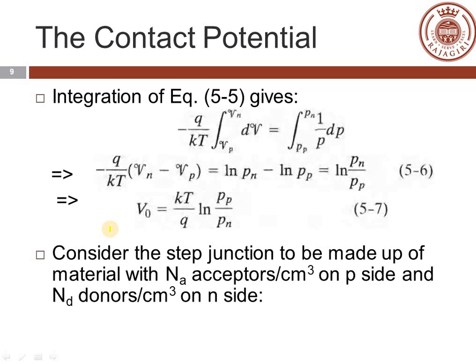Then we can write Pp Np is equal to Nn Pn, which is equal to ni square, which is the same as the equation we have studied earlier, n0 p0 equal to ni square. Equilibrium hole concentration into equilibrium electron concentration equals the square of the intrinsic electron concentration.